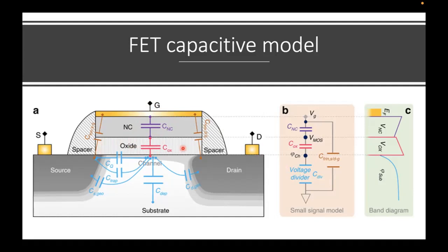And as the gate oxide layer is extended to include a portion of a source and a portion of a drain, then we will also have a gate-source capacitance and a gate-drain capacitance, as you can see. This is simply due to this overlapped area extended from the gate oxide to cover some of the source and some of the drain. So these are the first capacitances.